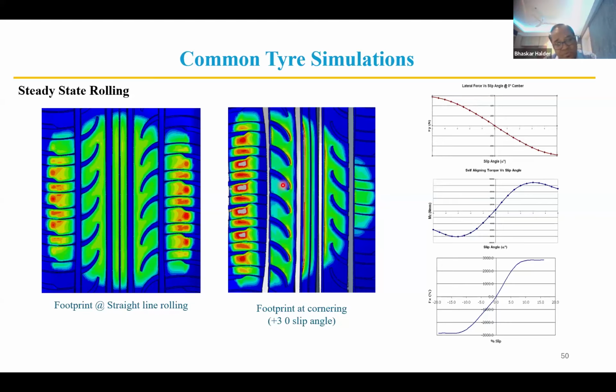So in this FE simulation, we can predict how it happens if I go for a higher steering angle. Whatever our application practice is, we can generate it here in the FE simulations, and judge whether this area or this contact is perfectly okay or not.